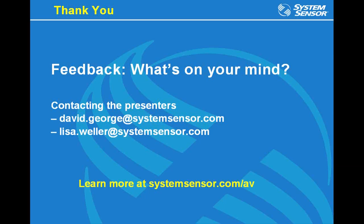I think we had this question on yesterday's webinar as well: can speakers that are labeled fire be used for messaging that is non-fire related? The answer to that question is no. When you are doing an emergency communication or mass notification system, even if it is combined with a fire system, your speakers either need to be plain or marked with the word alert, so that you know that whatever's coming out of that device is not strictly related to fire. It is called out in the military document and in NFPA that your speakers should either be plain or marked with alert.